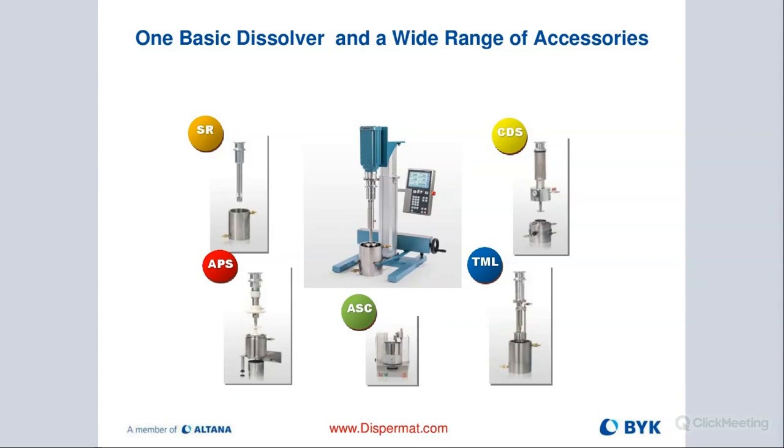But the way this system works is you have a container on top and the container on the bottom. In the top container, you have your slurry. You can pre-disperse in here with the cowles blade. When you reach the right particle size, then you swap out the blade and you change that to a milling disc, and you put your media, the beads, into the container on top.